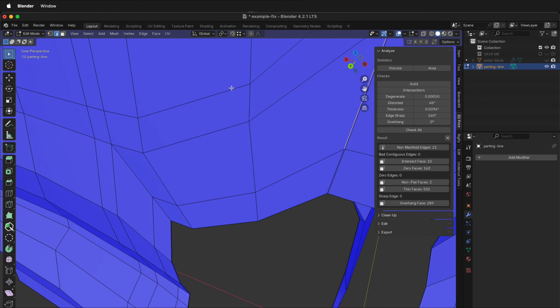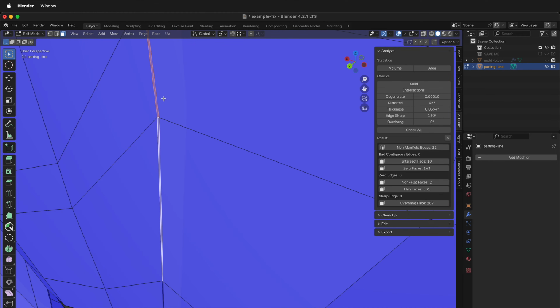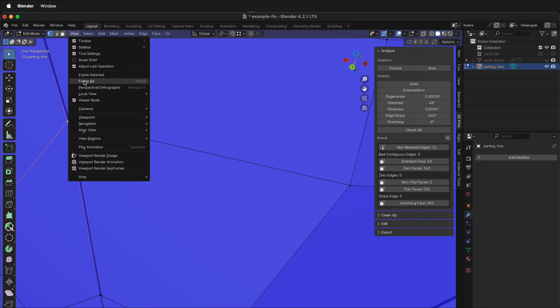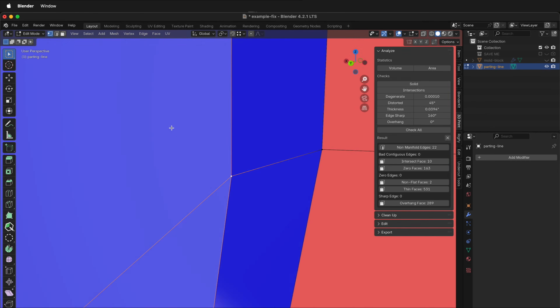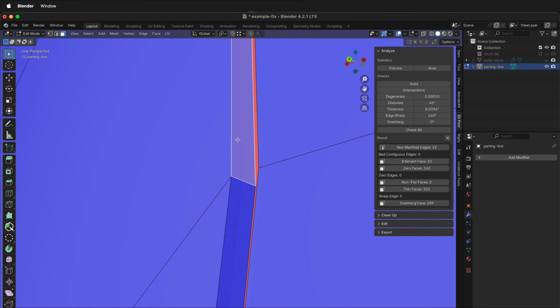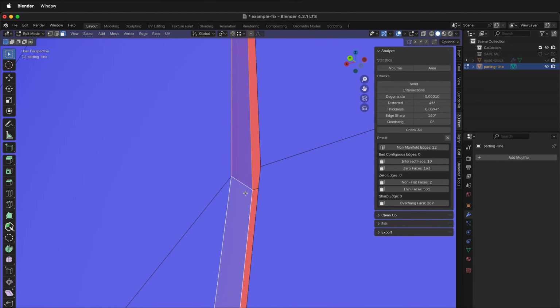So here, there are some interior faces inside here. Press 3, select the two outside skinny ones, press H, press 1, select that vertex, View, Frame Selected. Now we need to determine which ones are the extra faces. Press 3, select this face. If you see 4 edges around it in a narrow way, that's going to be the face. The same with this one.